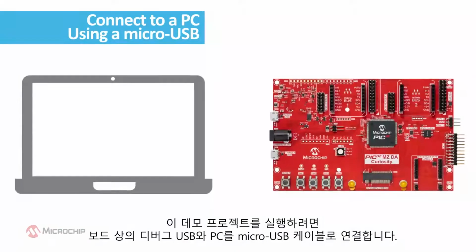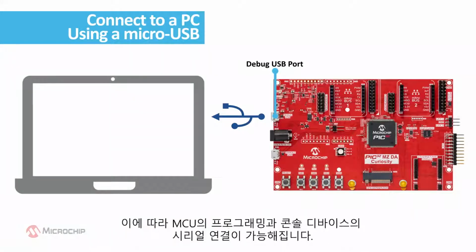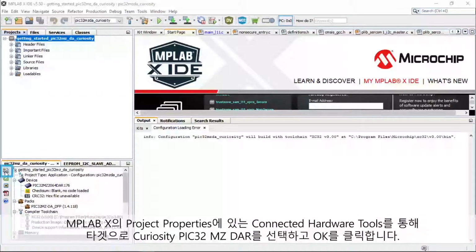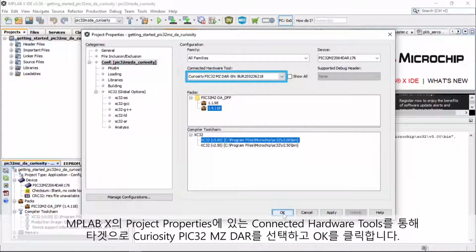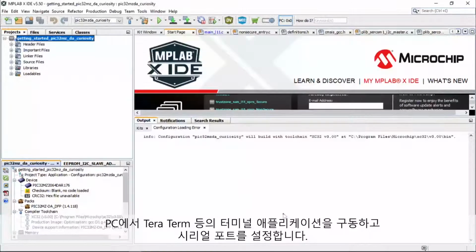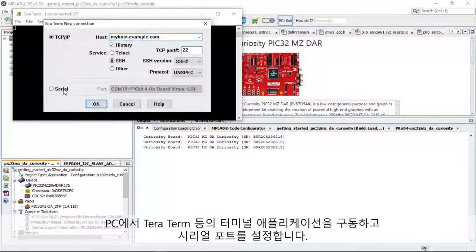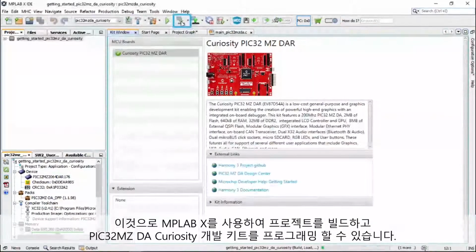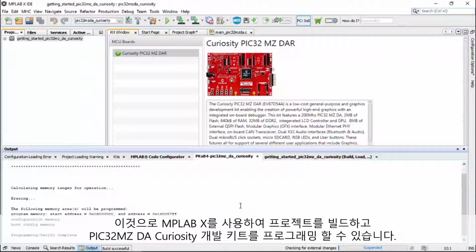To run this demo project, connect a micro USB cable between the debug USB on the board and a PC. This enables the programming of the microcontroller and provides a serial connection with the console device. In MPLAB X, under Project Properties, select the Curiosity PIC32MZ DA as the target kit in the Connected Hardware Tool dropdown. Then click OK. Open a terminal application, such as Tera Term on your PC, and perform the serial port setup. You can now build your project and program the PIC32MZ DA Curiosity Development Kit by using MPLAB X.